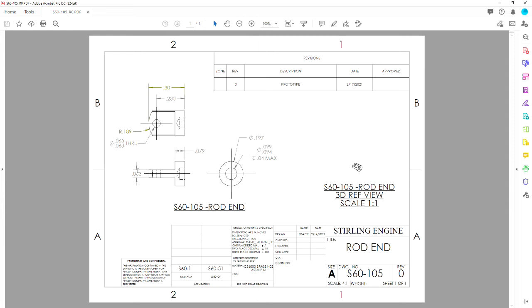take on this one. So our front view, we want it to be this ultimately. So we would want that to appear on the front view of the sketch plane. And in this top view, it's apparent that it's got rounded edges with some flats cut on it. So that would suggest that we probably should start off with a Revolve Base. You don't have to. There's more than one way to make this.